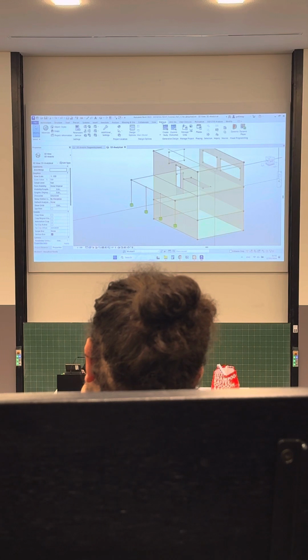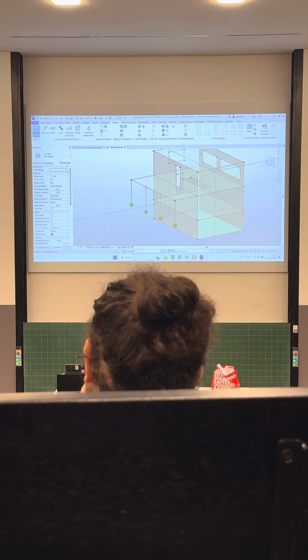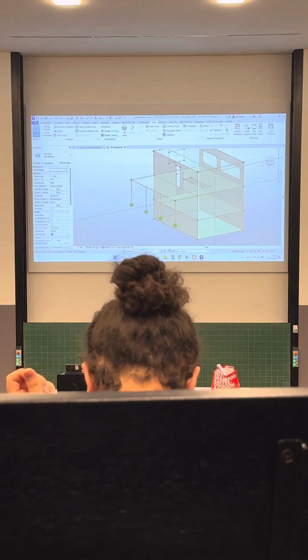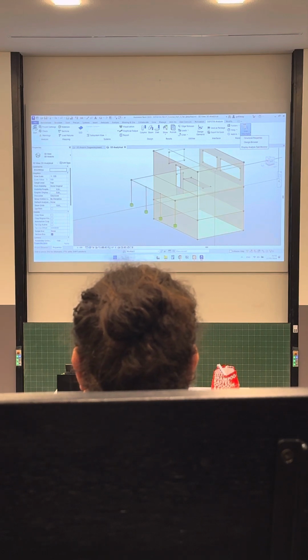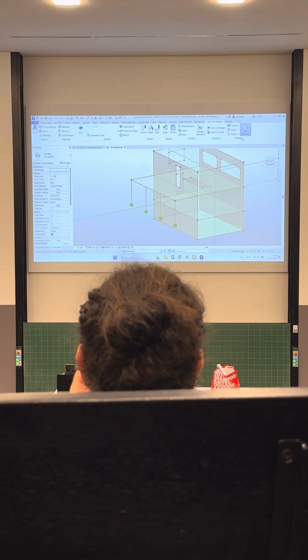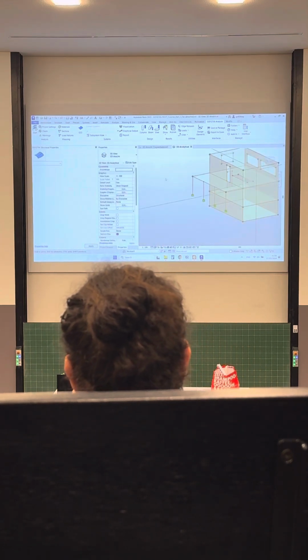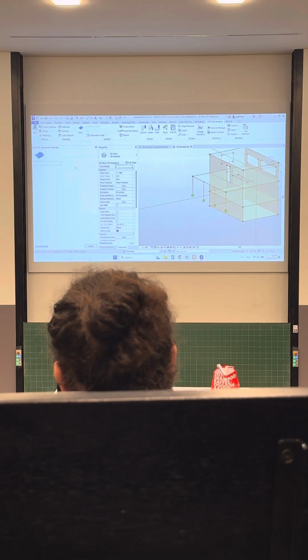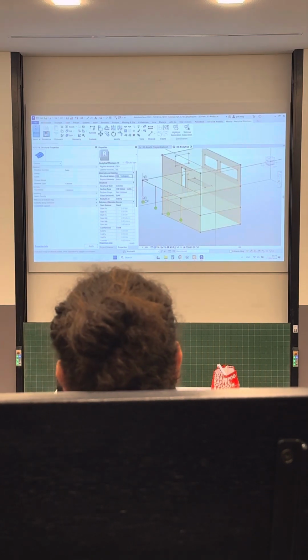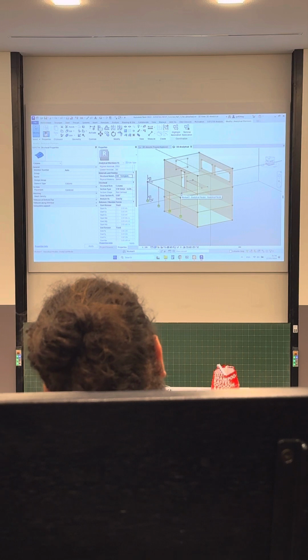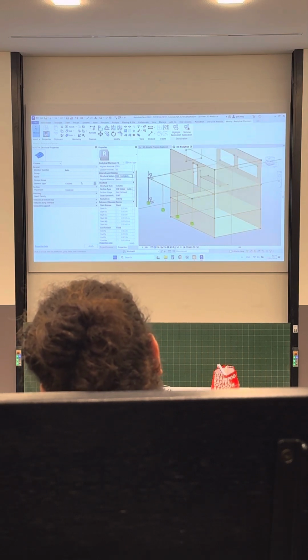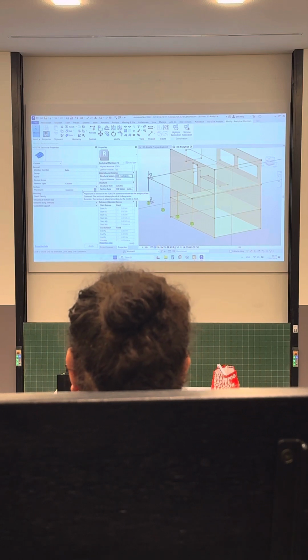Another thing to show you. Here, let's go to the structural analysis, to user interface and structural properties. And when you click here, you get another Sofistik tab, a new one. And when you click on your analytical model, here you can check how your Sofistik layer will read your elements. For example, this beam will be read as a column, and its section is centered.